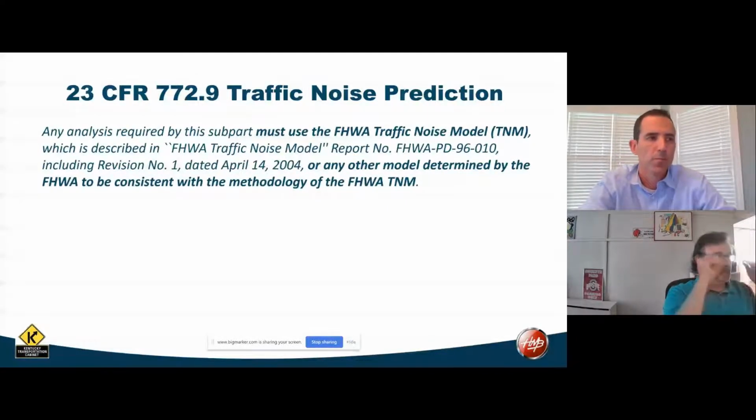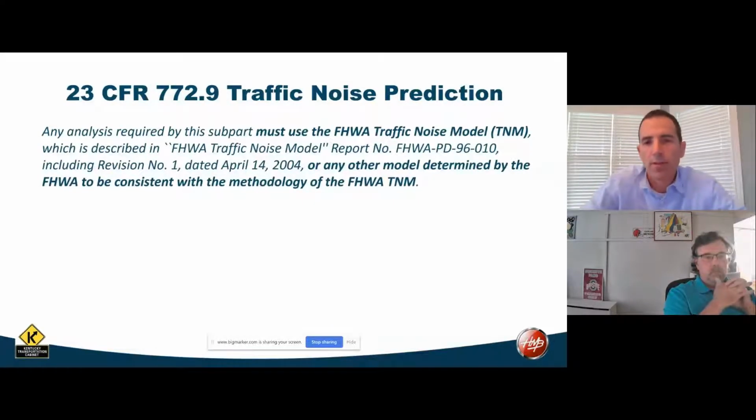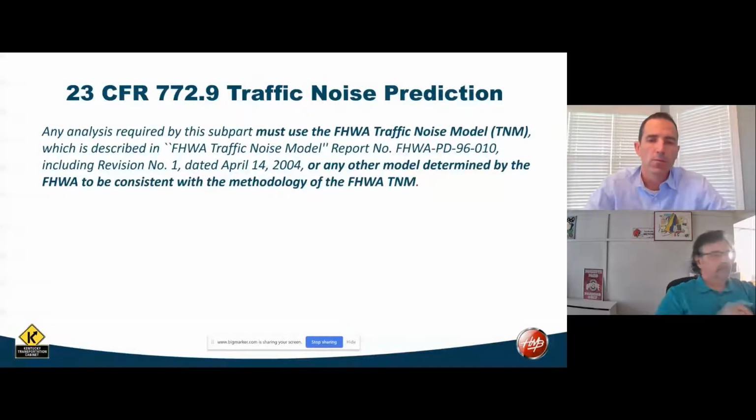They didn't want to have to do a full-blown analysis for every type 1 project like they're doing now. Our first discussions were based around 23 CFR 772.9, which says that you have to use FHWA's Traffic Noise Model software or another model determined by FHWA to be consistent with the methodology of that program.